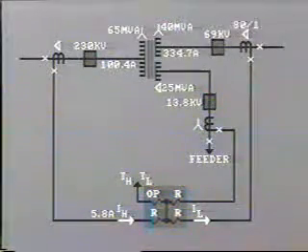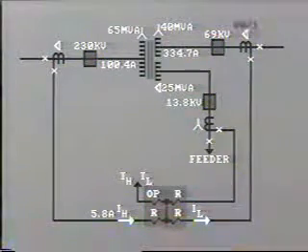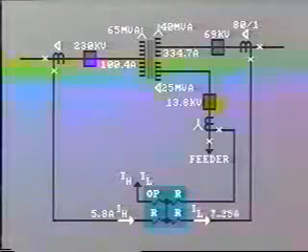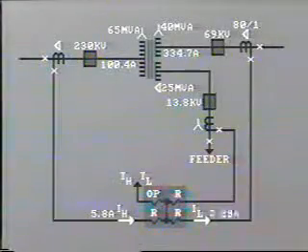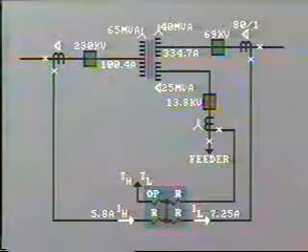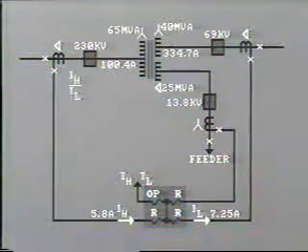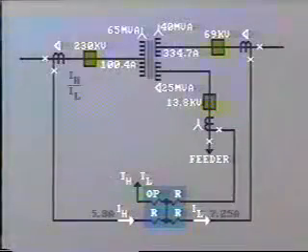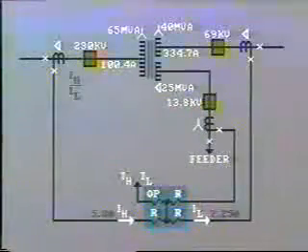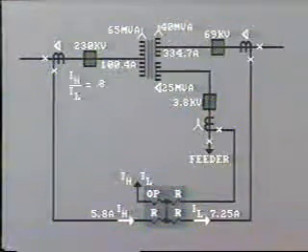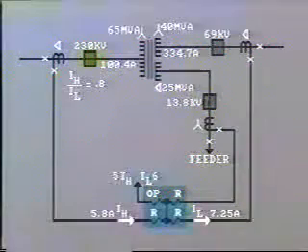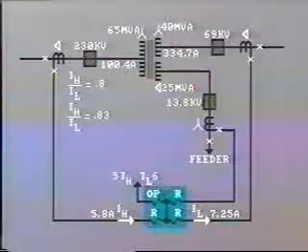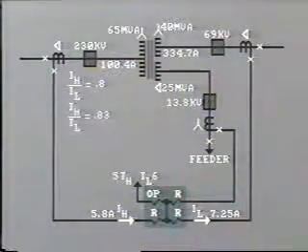Assuming a CT ratio of 400:5, that is 80:1, and remembering the delta connection, the CT secondary current will be 7.25 amperes going to the relay. The ratio then between IH and IL equals 5.8 divided by 7.25, or 0.8. Now, let's suppose that our taps are set on 5 and 6 respectively, giving us a tap ratio of 0.83.